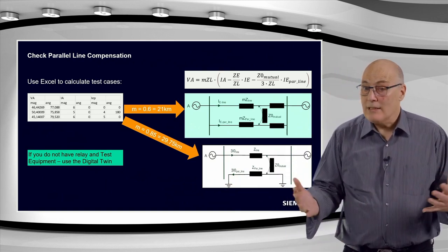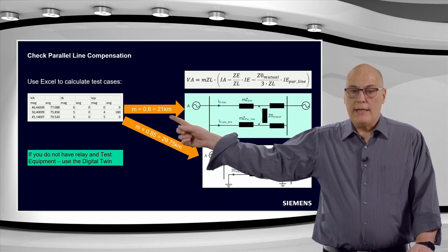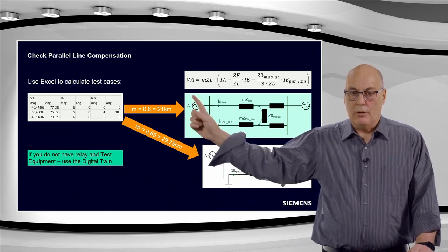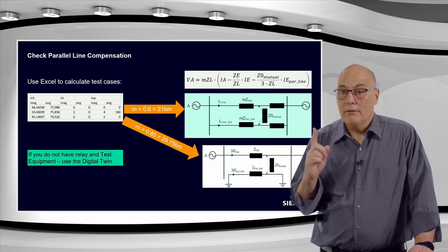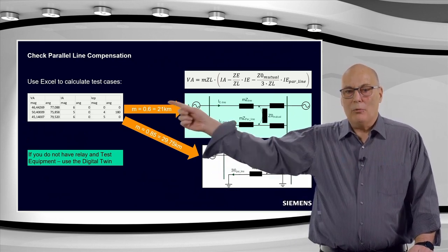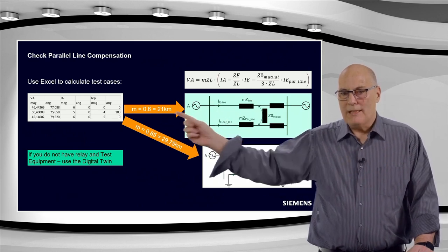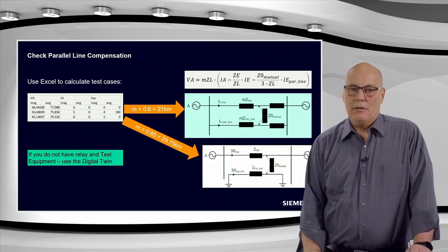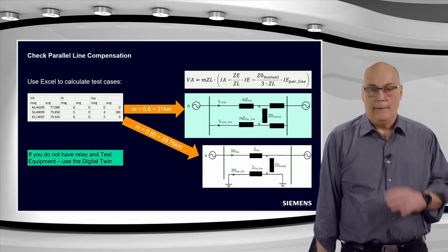That's what we expect. And that's the risk that this final case can give you an overreach. You can see we have the same current in the third test as in the first test on the protected feeder, but a smaller voltage. And the fault is further away. Remember, for the first test, the fault was at 60% and gave you 46 volts, and for the bottom test, the fault is at 85%, and you still get a smaller voltage. That is the significance of the parallel line infeed.